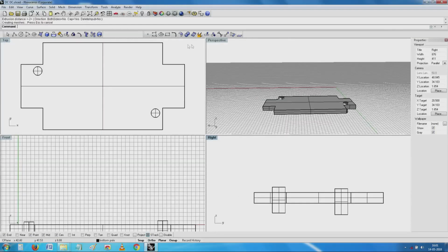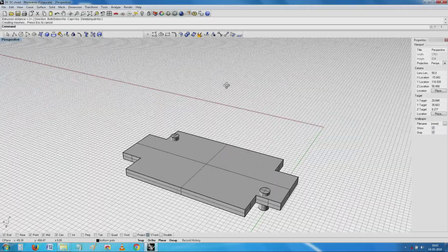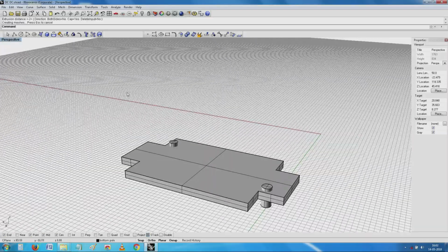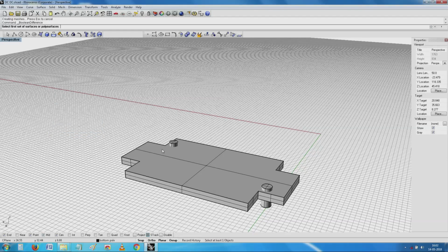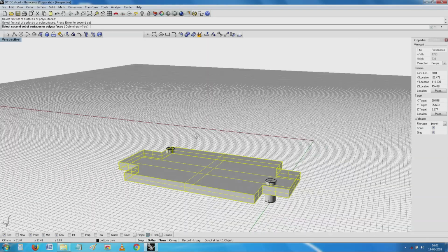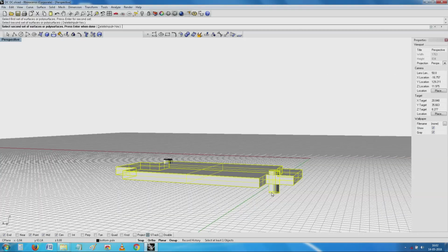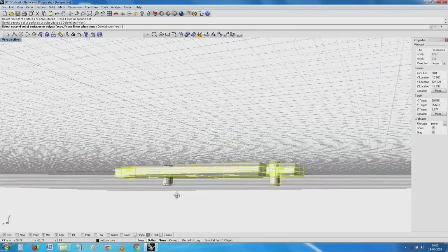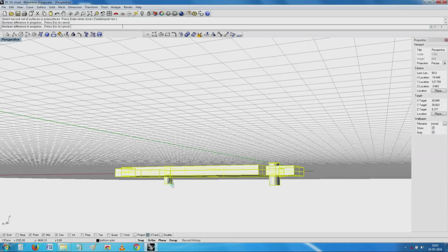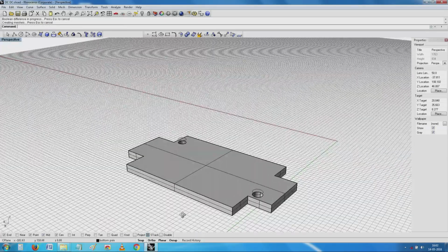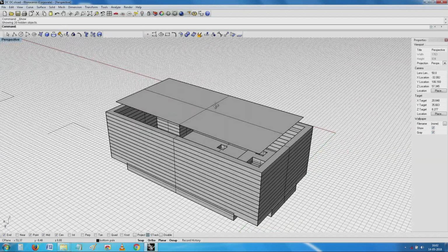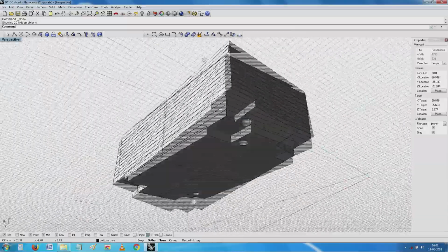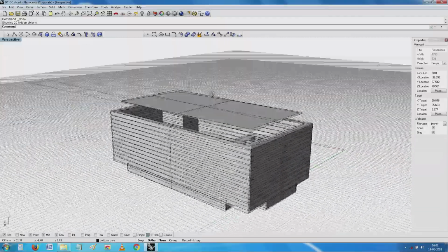So, when I make this Boolean operation, one of the first things that will happen is, I will have those nice holes, which will take place very well. See, I have got these nice openings. Now, I will go back and unhide the whole lot which I have here. Yes, this is where we were starting.